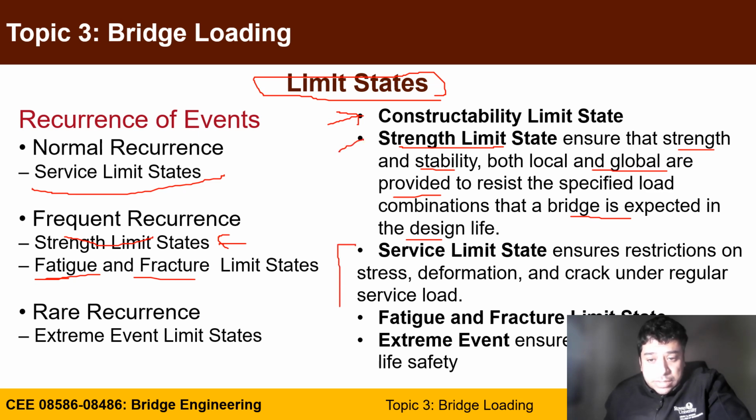For the service limit state, it ensures restriction on stress, deformation, and cracking under regular service. So you don't need to exceed certain cracking limits or deflection limits during daily operation. You have fatigue and fracture, which is material specific, especially for steel. You have the extreme event, which is also to ensure life safety of the traveling public.